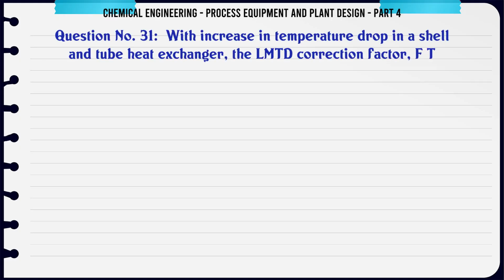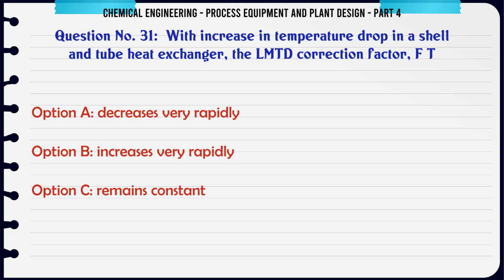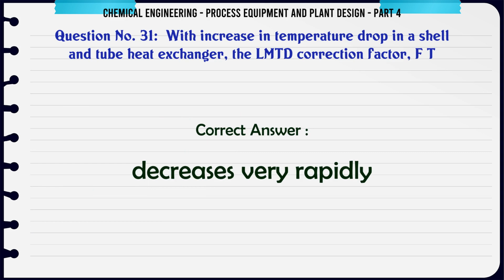With increase in temperature drop in a shell and tube heat exchanger, the LMTD correction factor Ft. A. decreases very rapidly. B. increases very rapidly. C. remains constant. D. increases linearly. The correct answer is decreases very rapidly.